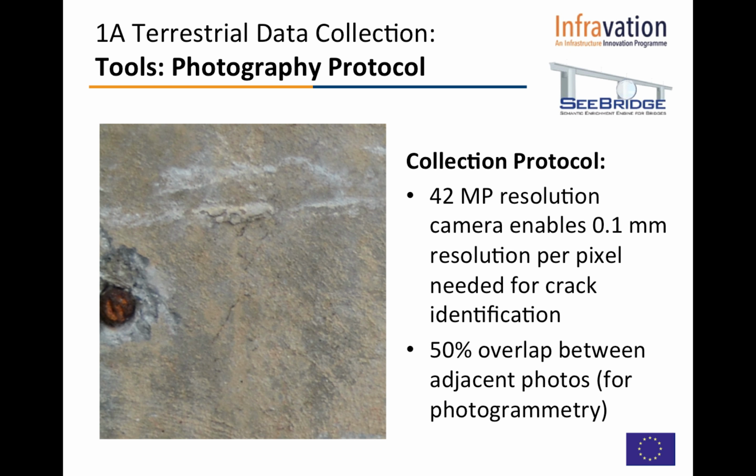And then secondly, the key thing here with this photogrammetric process, where these photographs are applied, we needed a lot of overlap. To be able to see the same spot in a number of photographs allows us to determine distances and measure accurately. So there was a high level of overlap needed. So we couldn't just take one picture of the side of a column, we had to take multiple pictures.